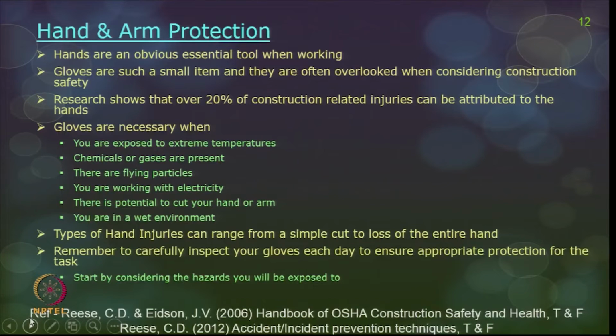The workers feel they lose their grip when they are wearing proper gloves. And research shows 20% of construction related injuries are attributed to the hands, and gloves are necessary under certain situations. Number one, when you are exposed to extreme temperature, or when chemicals or gases are present, when there are flying particles, when you are working with electricity, when there is a potential to cut either your hand or your arm, and when you are working in a wet environment, it is better to choose a pair of gloves.